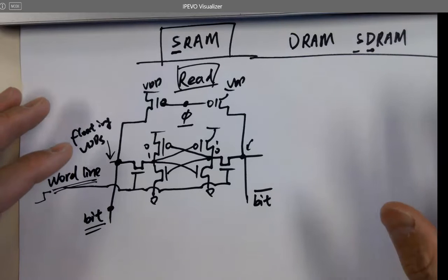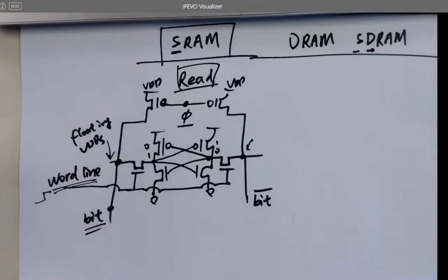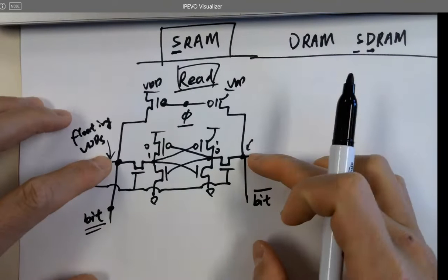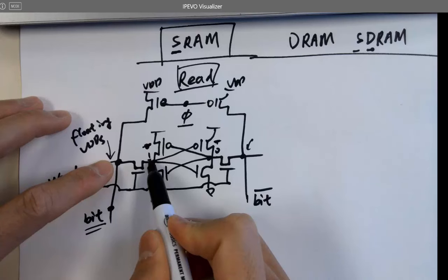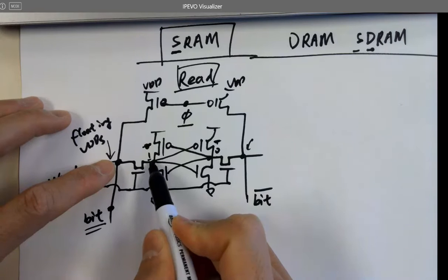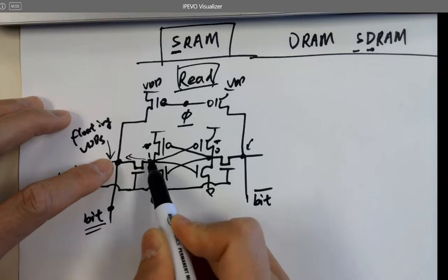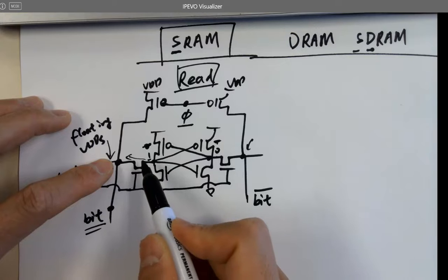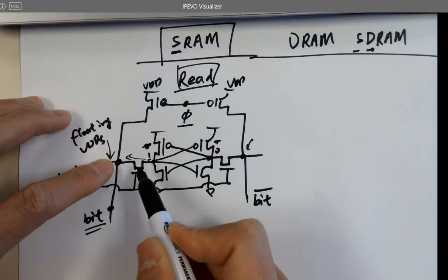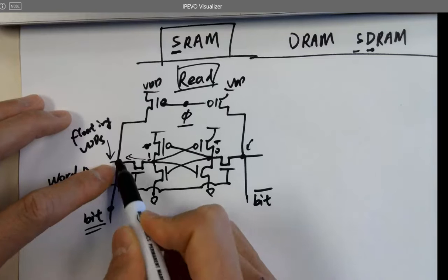So first, why don't I want to use a floating ground at the very beginning? When I'm resetting it, just floating ground to these two points. If I'm reading 1, 0, what's going to happen? Reading here, 1 here is a strong 1, right? It's a floating 0. What's going to happen? Your 1 is going to pass, right? But you are not passing the whole 1 because the NMOS is not able to pass the entire 1. It's like 1 minus VTHN, right? So it's bad. So let's pre-charge it to VDD. Then you can get the whole VDD.